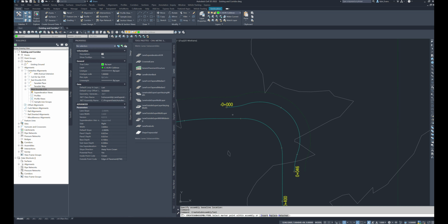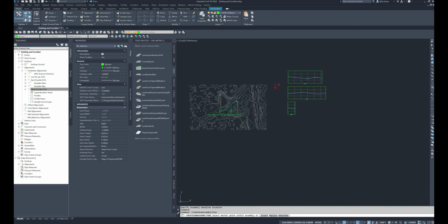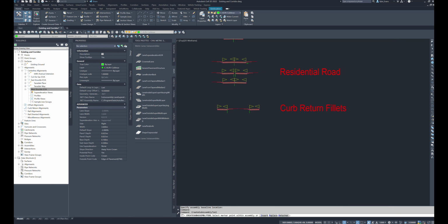So we'll need the driving lane on the right or the left, and we are going to need the sidewalk bits on the right or the left. We'll just have to remember that this alignment is our center line, driving's on the right, sidewalk and stuff is on the left. So I am going to right now switch this to left. I don't care about the width. If you really want to set it for 4.25, go for it. The slope is -2.